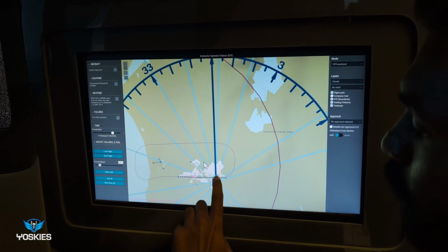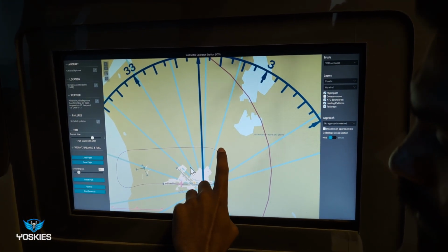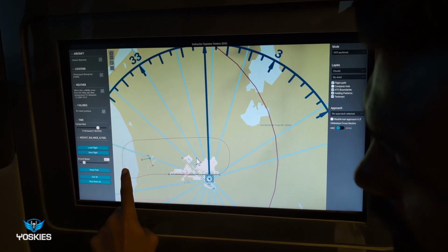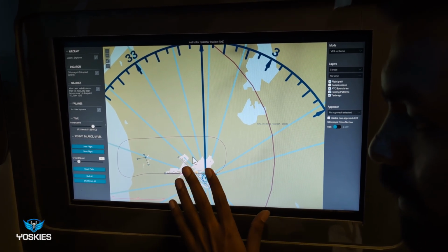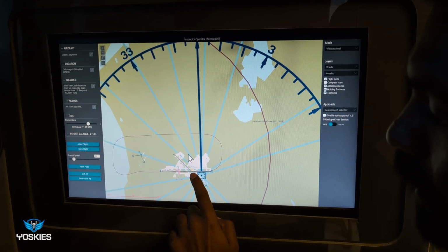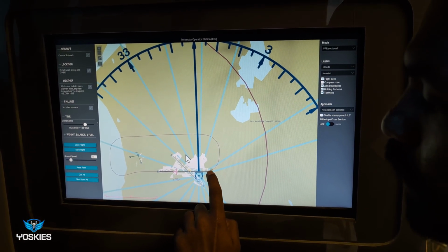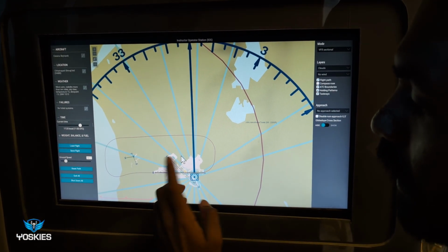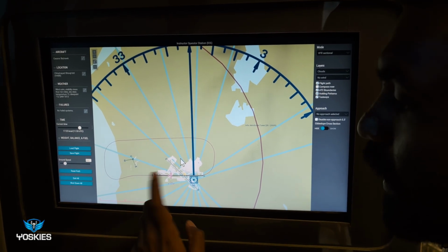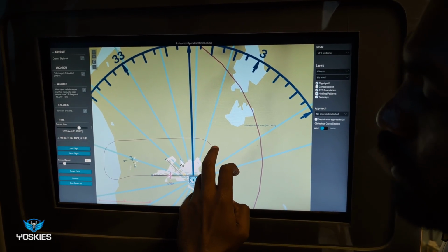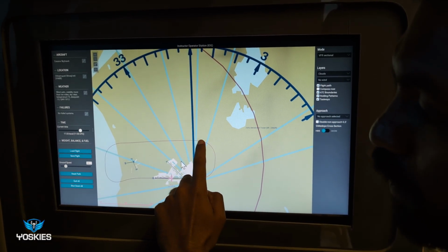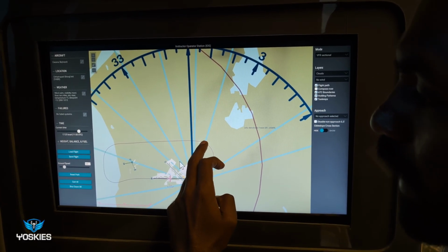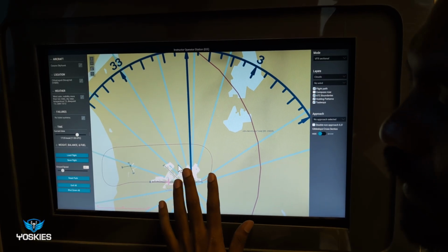So this is your upwind leg, this is your crosswind leg, this is your downwind leg, this is your base, and finals. All the turns that you make are going to be standard rate turns. So the first turn will be at 500 feet, then to the left hand side. Then after a couple of seconds, once you make 45-degree angle with the numbers basically, that's when you want to start turn to the downwind towards left and continue, and then level out at 1000 feet.